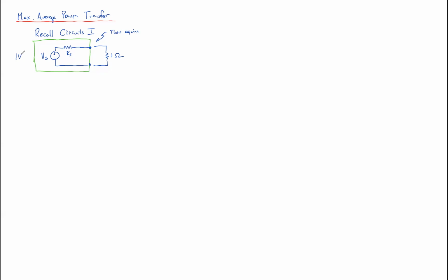But that RS is getting in the way, and that RS is limiting that voltage. And if that RS was, say, hypothetically 1K, it would drop almost all the voltage. And now you'd be only limited to getting about 1 millivolt across this 1 ohm resistor, which would create 1 milliamp of current, which would create only about 1 microwatt of power, like a millionth of what you'd like. So try again, Jesse, and tell me now what you'd like RS to be if this was a perfect source.